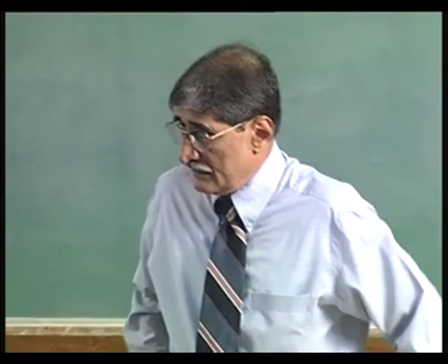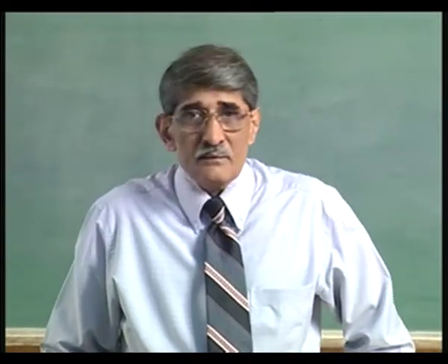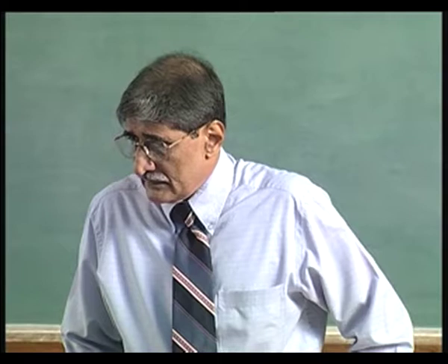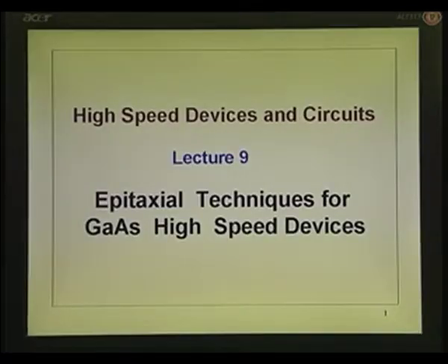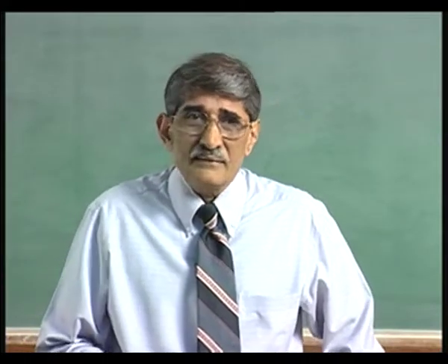Okay, we begin our discussion on epitaxial techniques for gallium arsenide, which will be used for high speed devices. Yesterday we discussed in detail how to realize semi insulating gallium arsenide material, because when you want to make a device or integrated circuit, what we discussed yesterday was you need an insulating substrate, if not insulating, at least semi insulating.